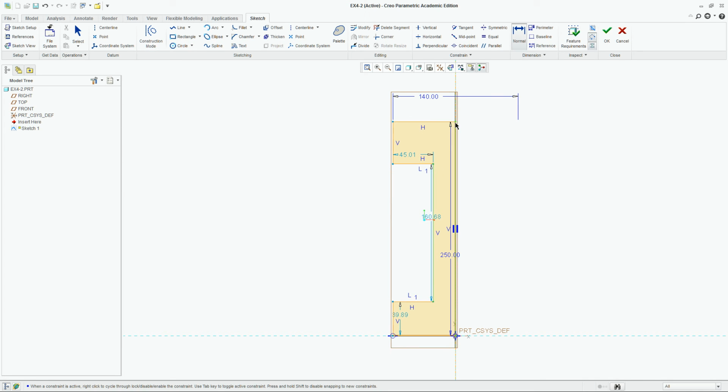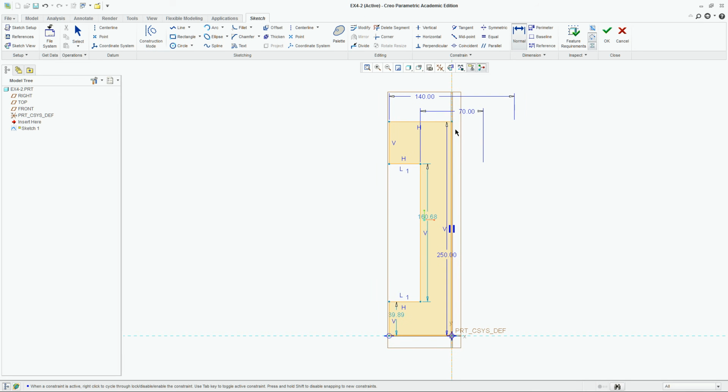So click on the object line, the center line, the object line again, middle click to place it, put in your entire diameter. This way you don't have to deal with any type of going in and making sure that you've divided correctly and everything else. So this dimension right here is going to become 40, and I am going to set equal lengths between here and here.